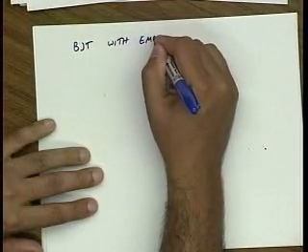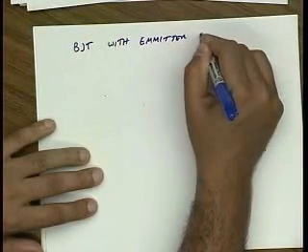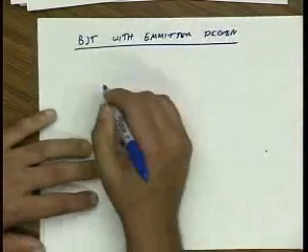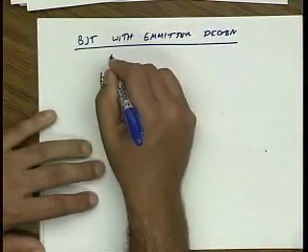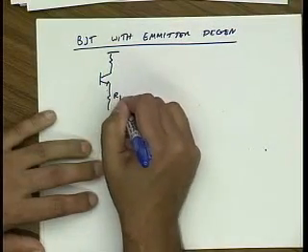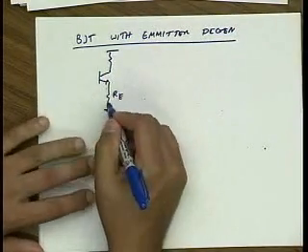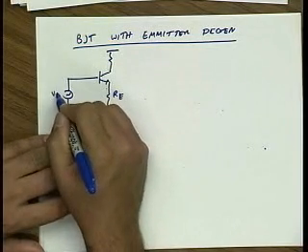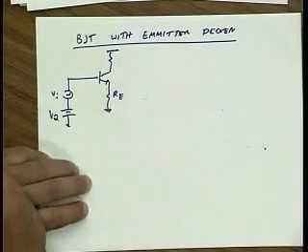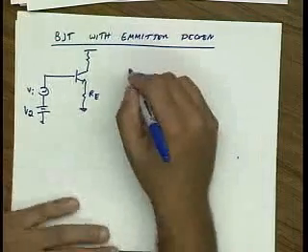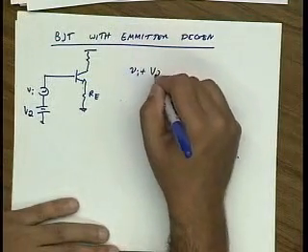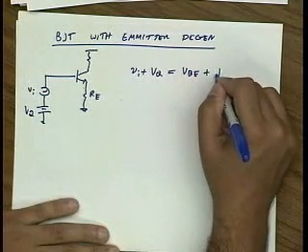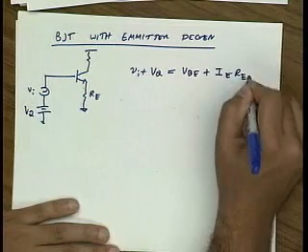Okay, so let's do an example of a BJT that we did last lecture, but now with emitter degeneration. So now I have some resistance RE here. And again, let me drive it with an ideal voltage source Vin, and I'll bias up at VQ. So my input signal is Vin plus VQ, which is equal to VBE plus IERE.